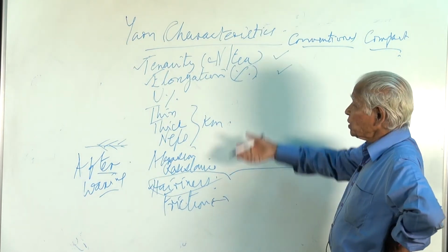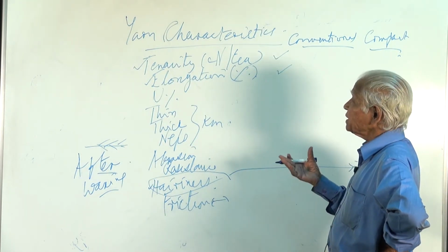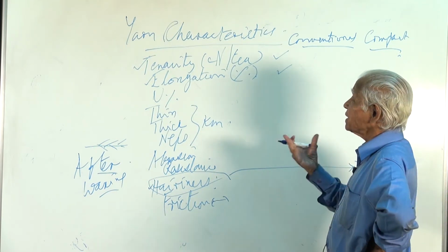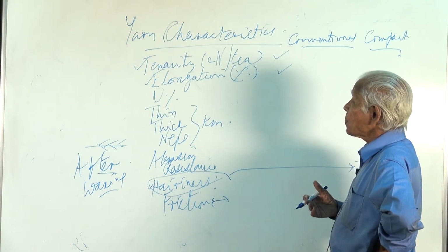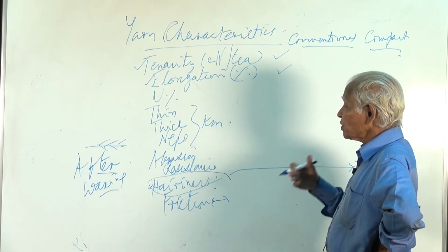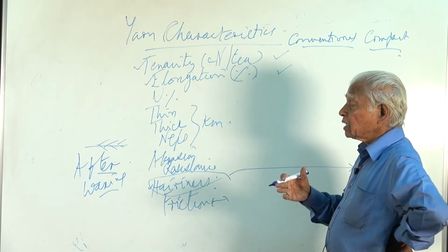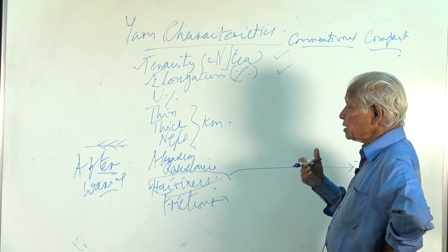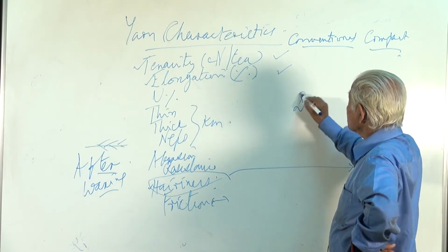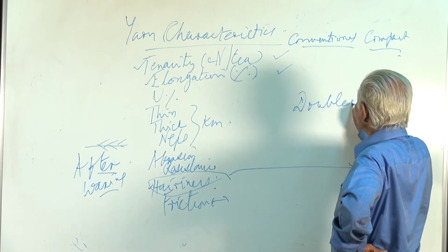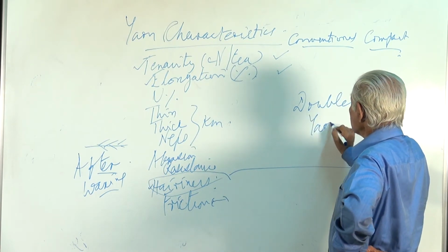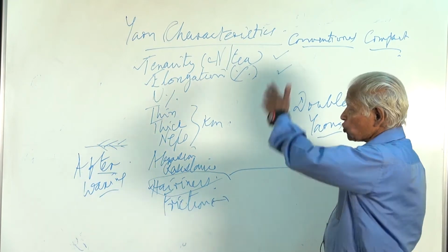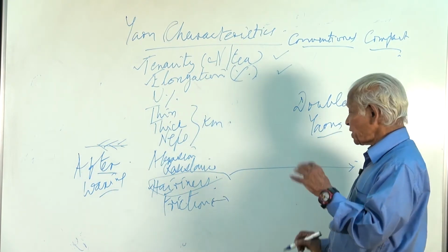So when we get a report like this, we are in a position to see the performance of the yarn, how good the yarn is, and take a decision for purchasing that for a particular item like shirting or a knitted fabric, or see, for suiting we use doubled yarns. So generally doubled yarns are not tested for so many properties because they are supposed to be uniform.